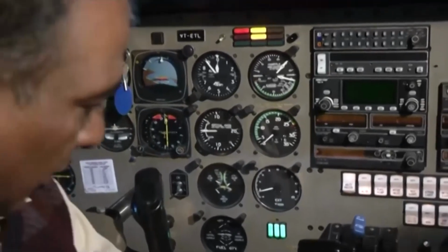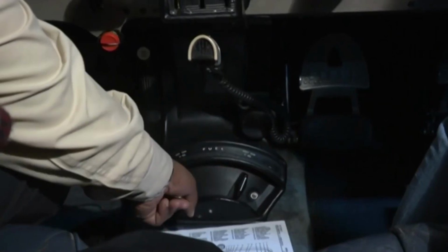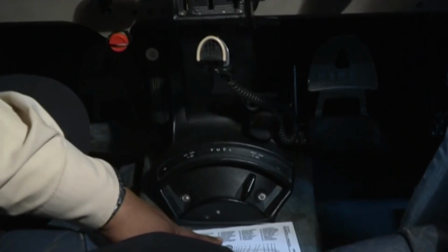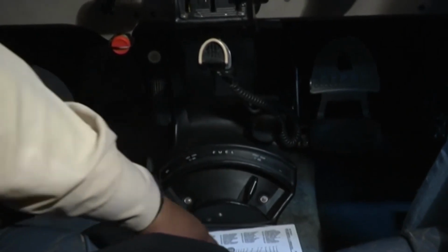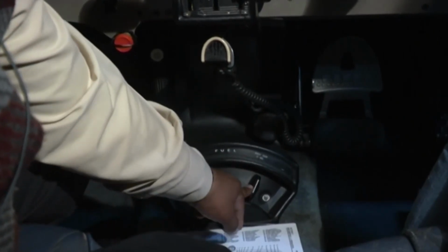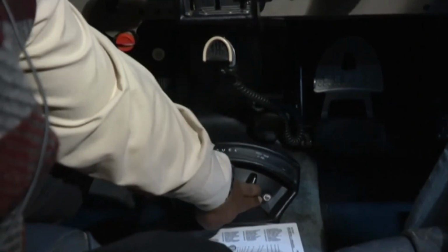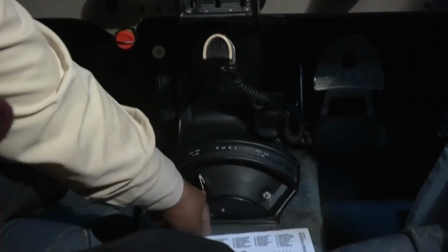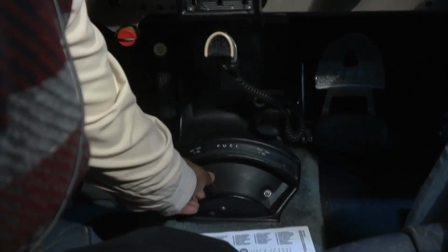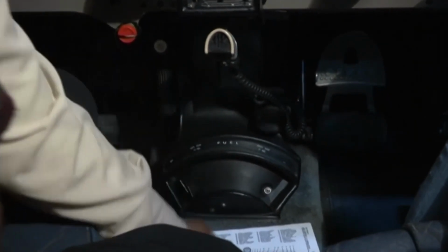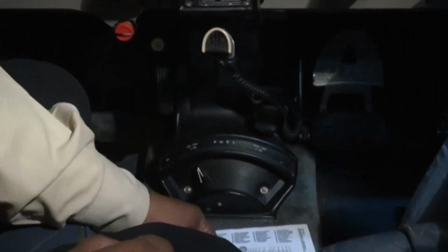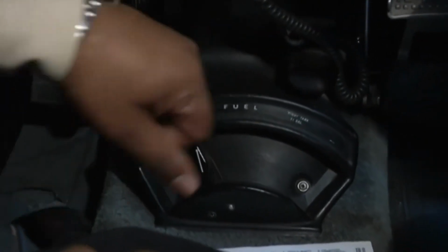Then here you can see this is your fuel tank selection. As I have earlier told, there are 2 fuel tanks in this aircraft, one in the left wing and one in the right wing. This is the selection for the fuel tanks. This selection is for the right tank. That means the fuel supply will come from the right tank, and if I do it like this, on the left, the fuel supply will go from the left tank. And there is an off position also. If I have to shut off the complete fuel, now it is in the off mode. So you have 3 selections of left, right and off in this particular plane.